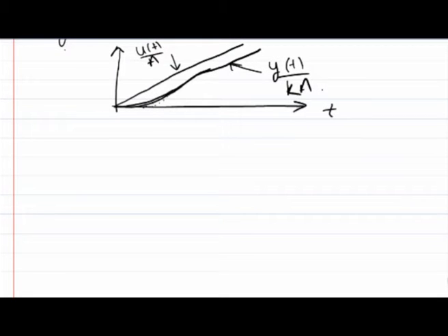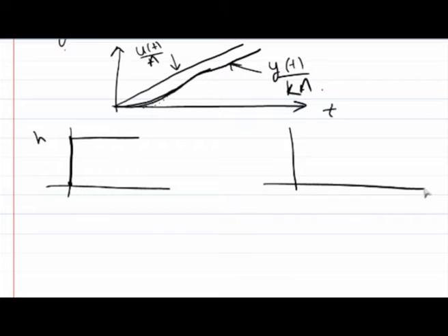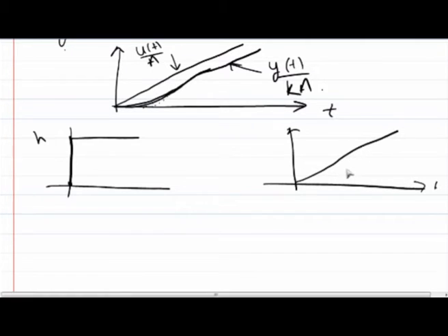Now think, to start a process, either we need a step kind of input, where at t equal to 0 I am at 0 level, and suddenly I drive the system to a value, let's say h, or another one is a ramp input. Or let's say I will give a time limited ramp input, and afterwards another ramp input would follow if required.